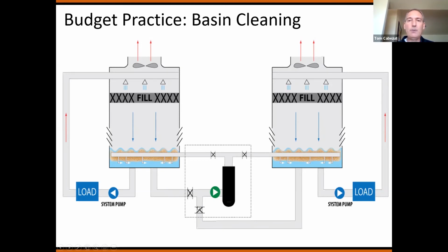The system's smaller, and we actually have a really nice design package system with the valves and actuators that tie to a PLC that can control all this out in the field. It's easy to program. You're not having to run a big pump. Let's say, for example, we had 4 cells and each of them required 300 GPM. That's a 1,200 gallon a minute system versus one 300 gallon a minute system.